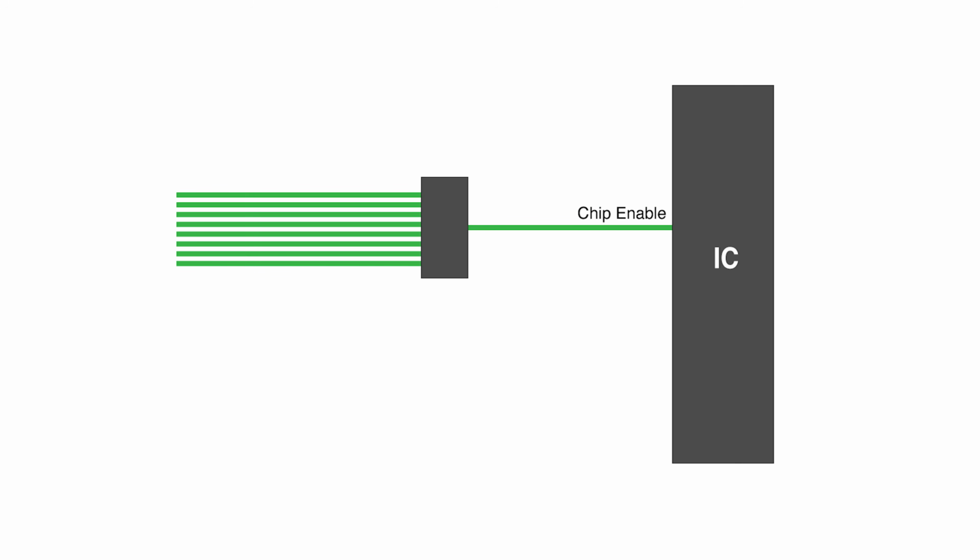The alternative would have been to have 8 bits coming into the chip, which would not be realistic and would require more pins than are available for a particular package size in the case of the gate array, or in the case of third-party chips, they would have to have external logic to convert those 8 bits into a single bit that would activate the chip. That would have made the computer significantly larger and more expensive.